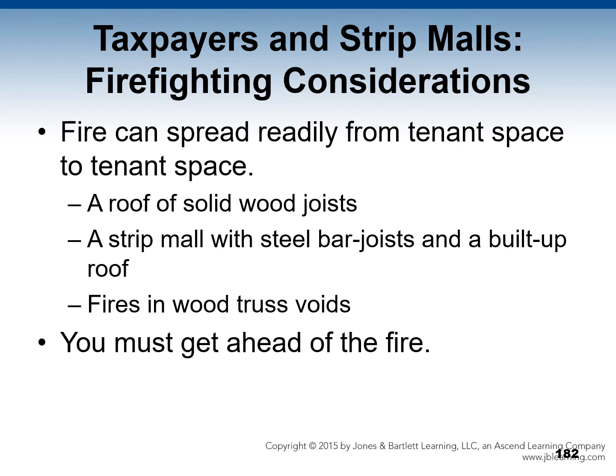You must get ahead of the fire. Fires in wood truss voids will spread rapidly due to the inherent openness of the truss. Ventilation can help slow horizontal fire spread through the roof area.